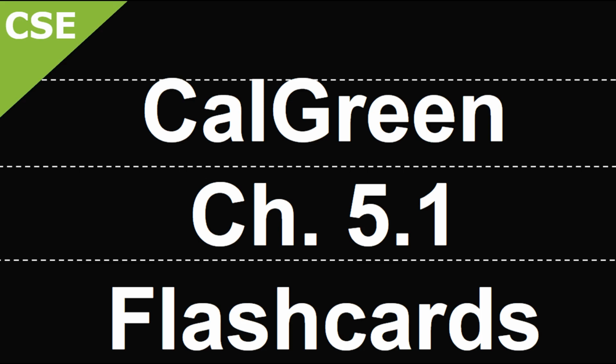There's one more electric vehicle charging station update. If you decide to install 2 low-power level 2 EV charging receptacles, then you can reduce the minimum of required EV-capable spaces by 1.